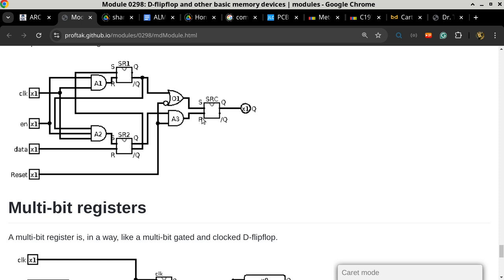Exactly. So somehow the blue screen of death has to do with the watchdog. That's because when Windows and Linux and Mac OS and all kinds of modern operating systems are healthy, there's a timer that goes off every so often, like every 10 milliseconds, 20 milliseconds. I don't know exactly the period of time, but anyway, they periodically hit the watchdog.